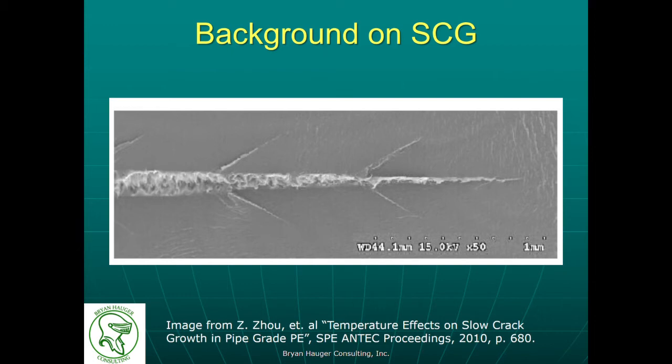Here, I'm showing my favorite digital microscopic image of a craze zone in polyethylene. In this single image, you can see the crack opening nature of the failure, along with the bridging fibrils which cross the craze zone. These bridging fibrils oppose the opening of the crack through their resistance to continued elongation.